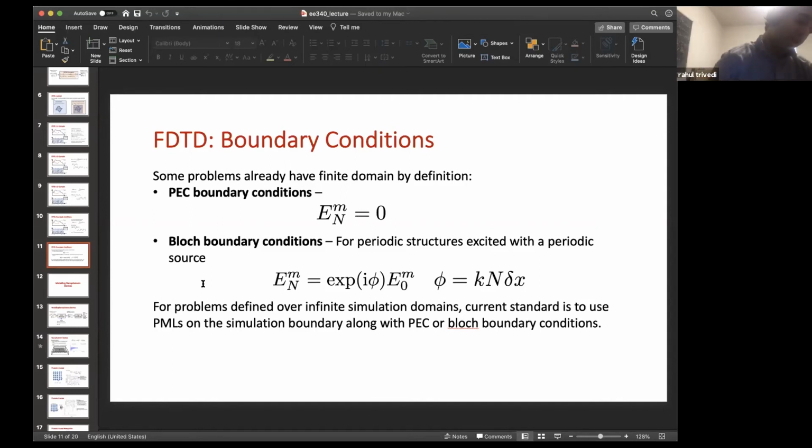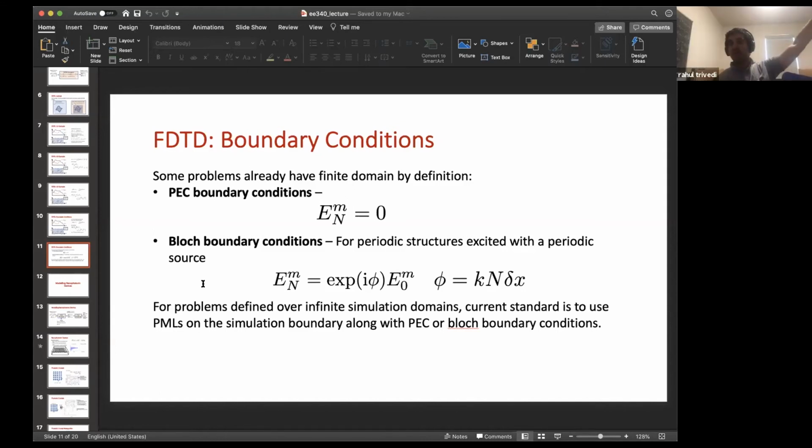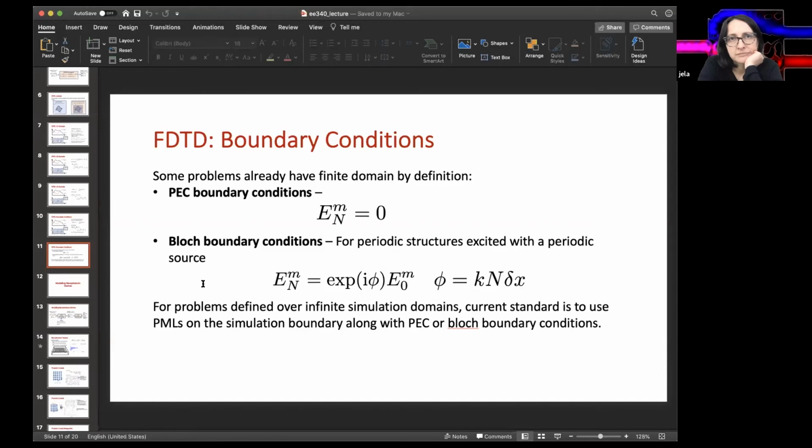Yeah, you're getting into a hypothetical scenario where your boundary has to be so far that you cannot really simulate that on any computer, right? So in theory, what you're saying works fine. If, for example, you have a waveguide based device, you want to calculate transmission inside the waveguide, and you want to ignore the fields that are radiating away, not into the waveguide mode, and you send in a pulse which is narrow in time, you can keep track of when the pulse comes out of the waveguide but is not really interacting with the boundaries, and at that point take your data and analyze the transmission.